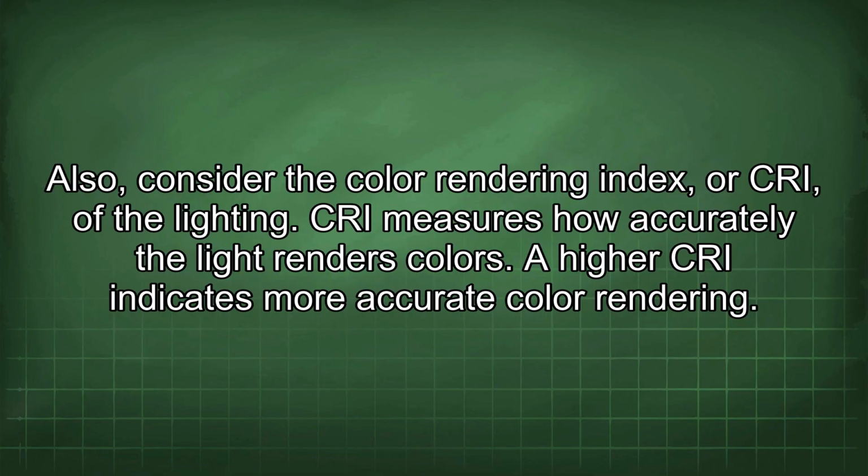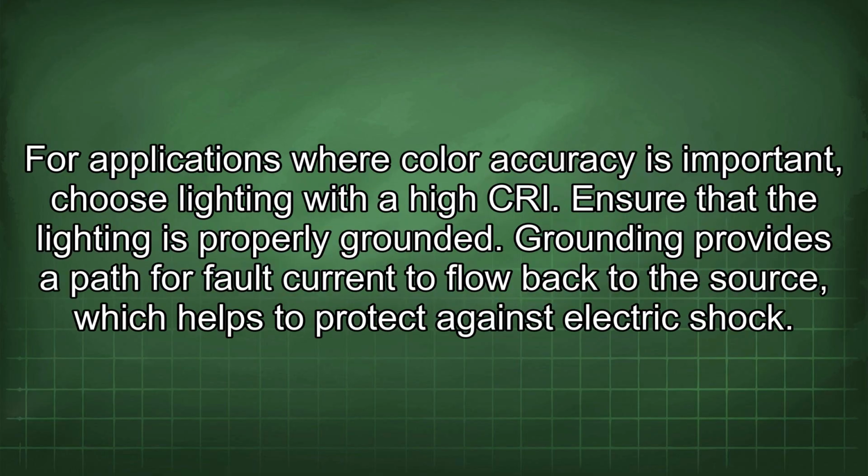Also, consider the color rendering index, or CRI, of the lighting. CRI measures how accurately the light renders colors. A higher CRI indicates more accurate color rendering. For applications where color accuracy is important, choose lighting with a high CRI.